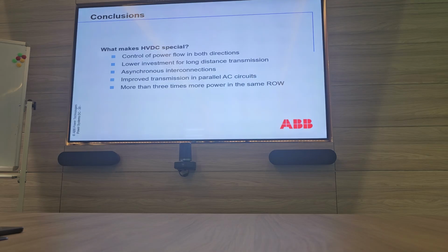If it's more than 1000 kilometers, ultimately they will go with overhead lines. Also, if the connection is around cities, they need to use cables, because inside cities they can't transfer with OHTL.